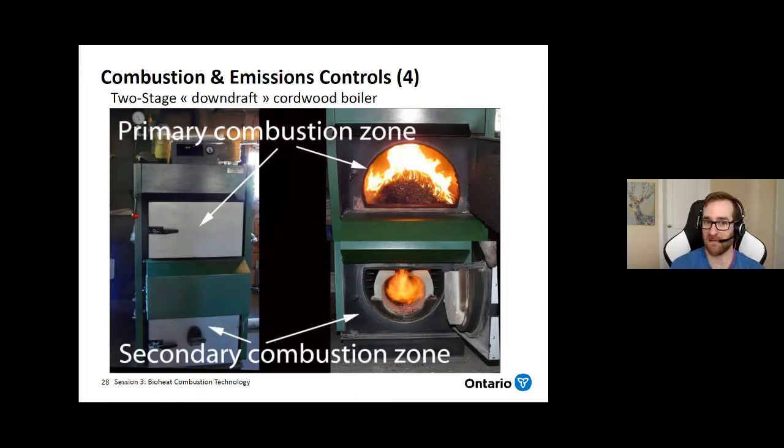You wouldn't really have a fire in the primary combustion zone when the unit is in normal operation, but you'd have pyrolysis, so the wood would be cooking in there and smoking. That's key, to separate those two phases so that you focus on burning the volatile fraction of the wood, which is 70% of the wood.